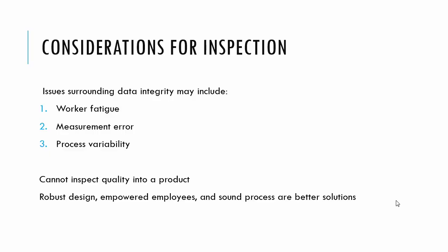When collecting the data from inspection, we should be concerned about how it was collected and how good it is. Issues may include worker fatigue. This could be workers making the product as well as the inspector's fatigue. Another issue to consider is measurement error. How accurate is the tool we are using to inspect? How accurate does it need to be?